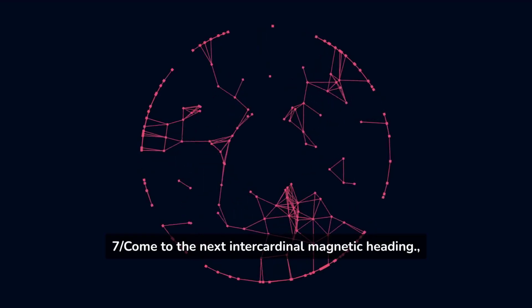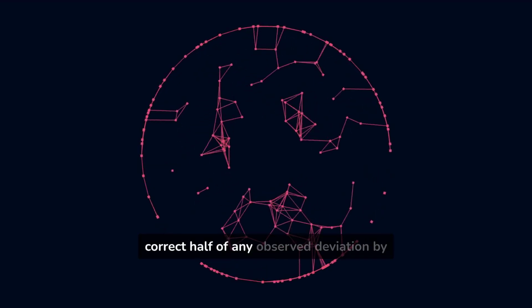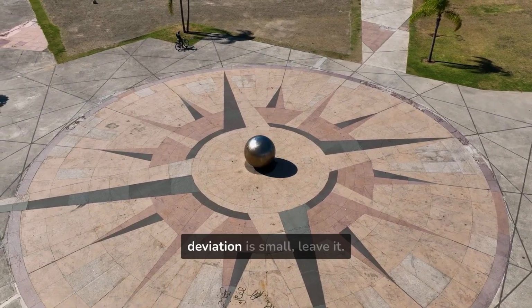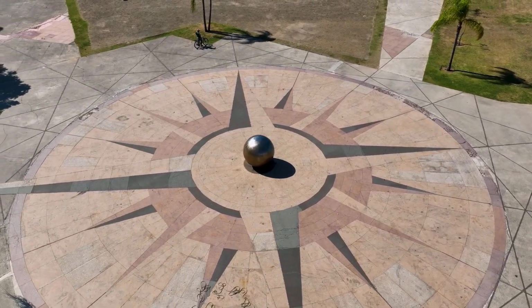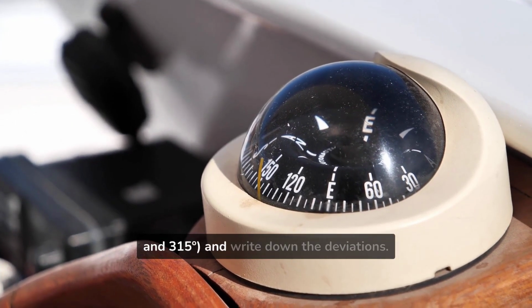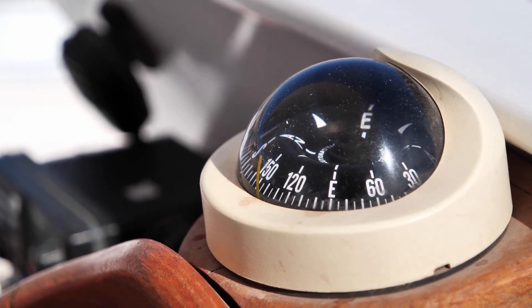7/ Come to the next intercardinal magnetic heading, 135 degrees, and correct half of any observed deviation by moving the sphere. Also, if the deviation is small, leave it. You can also check the two which remain, 225 degrees and 315 degrees, and write down the deviations.